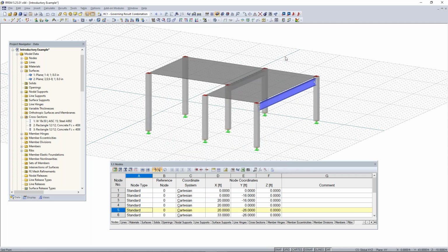Next thing to go over is the toolbar. At the top here, we have what's called our toolbar. If your toolbar does not look like mine and you would like it to, you can simply right click anywhere in this grid space, hit the reset to default button, and hit yes. Then all of the buttons for the toolbar will be converted into this default view. It just makes it a little easier to navigate.